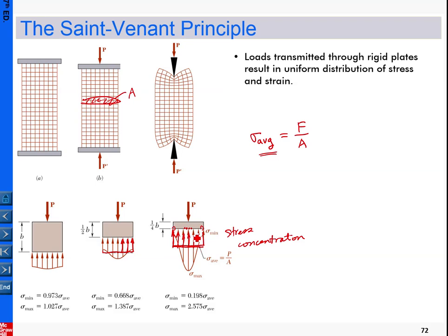So from here you can see the formula we learned is good, but in terms of estimation, it is a very rough approximation compared to the practical one. So the Saint-Venant principle reminds us to do our best to remember that in certain situations we must take care of this, such as stress concentrations here.